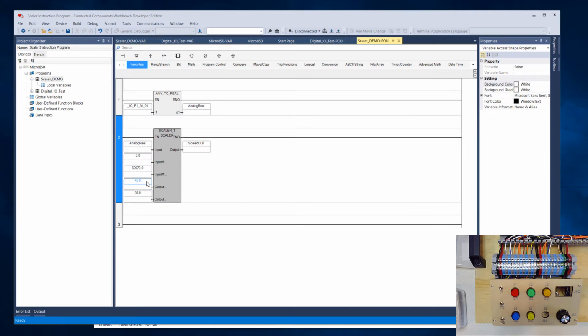So let's try another hypothetical to see how we could use some programming to change these instead of just using hard-coded values. So let's say now instead of having a fixed output range of 10 to 25 like you just did, or 30 to 45 like I have here, let's say we want to use this potentiometer to control the speed of something, but we want to have 2 modes. Basically, we might have a fine control mode where we want the motor to be running real slow, like let's say maybe between 0 and 5 RPM, and we could use that to creep up to an initialization point.